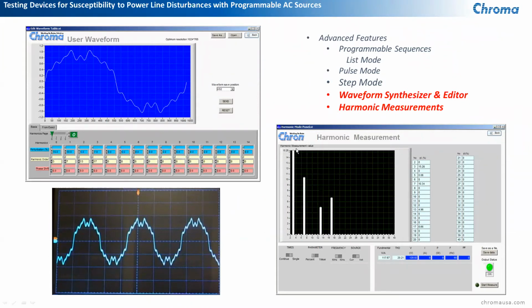And you can see right here on the display, it graphically displays the 3rd, the 7th, the 13th, and the 17th harmonic. So it captured it perfectly. We also get the raw data here for each of the harmonics. In this unit, we can go up to the 50th harmonic. I only displayed it up to the 40th because that's all I was using on this unit. We can do measurements even higher, up to the 100th harmonic on our 61500, 07, 08, and 09.